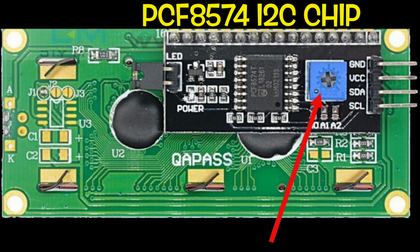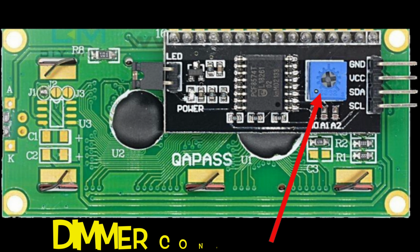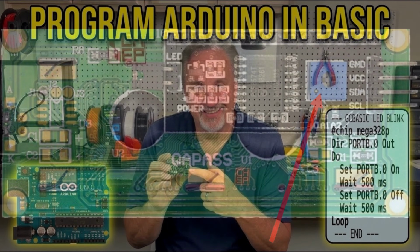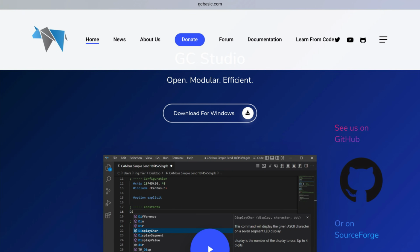Many of these have a PCF8574 I2C chip on the back to communicate with your microcontroller. Many of them have a built-in dimmer, and the dimmer type will actually determine which type of module you've got when you're writing your code. A lot of this is built into Arduino or Arduino libraries that you have to install. But as I showed in a previous video, you can actually program Arduino with the BASIC language. GCBASIC is that compiler, and it's free and open source and has a lot of this stuff already built in to make it so easy to control an LCD character module.